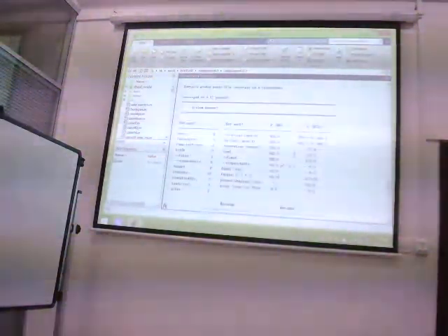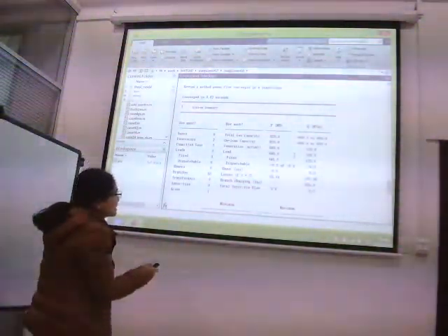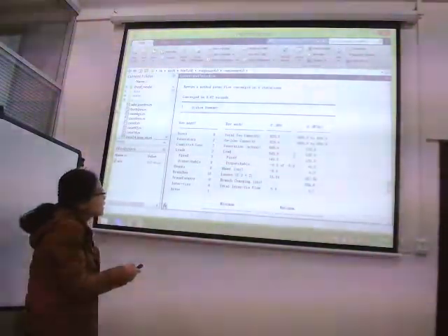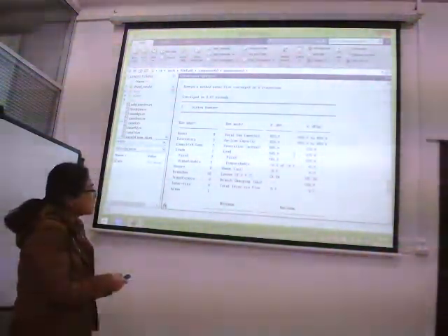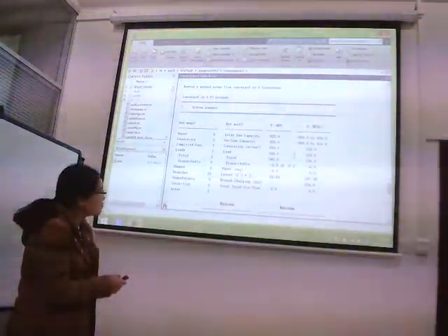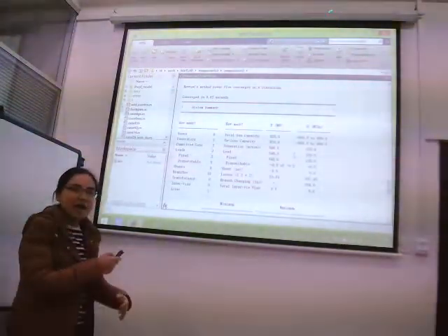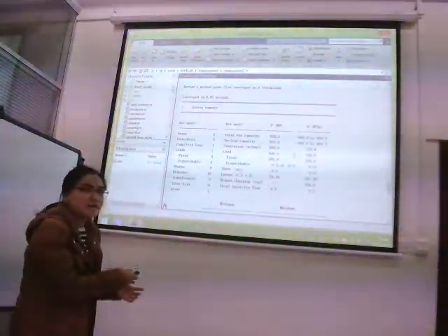But for this one, because we increase the load demand at bus 7, now we have 500 and 600 load, 50 and 45 load demand. And then adding the losses, we have to generate 560 generation to satisfy the load demand and system losses.